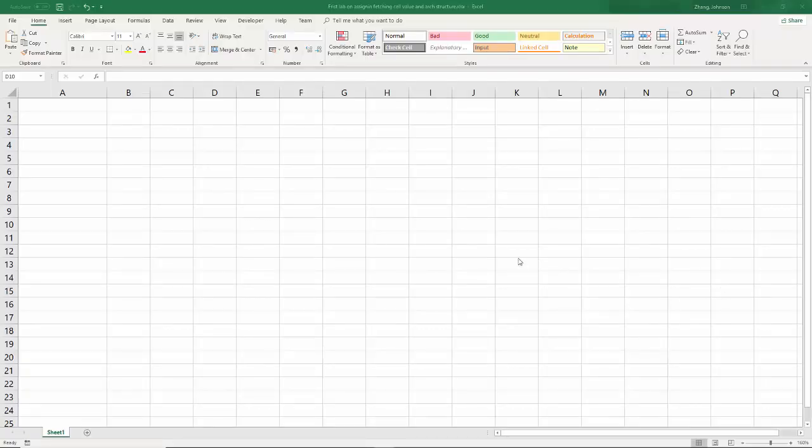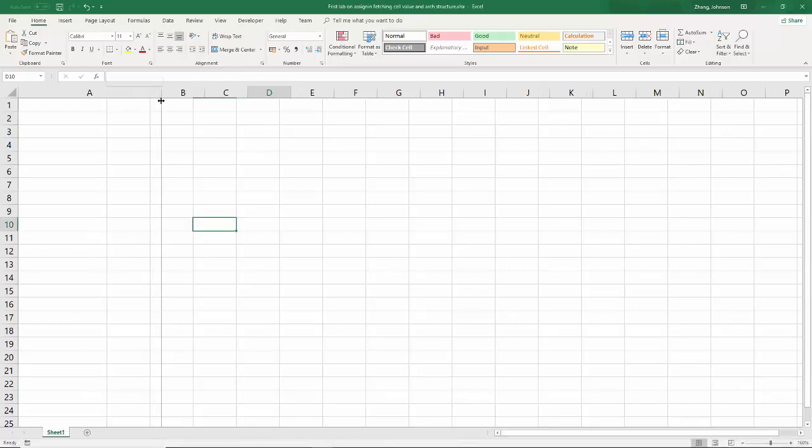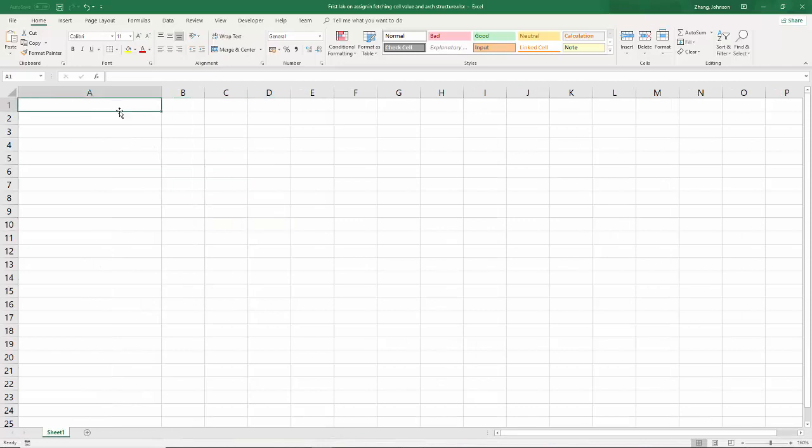Okay, now we have derived the equation to generate this small arch using the truss member. So let's try to implement this in Excel VBA programming. Let's open the Excel file as I show on the screen at the moment. Make sure that you open the first spreadsheet, and then we set up a few parameters in here.